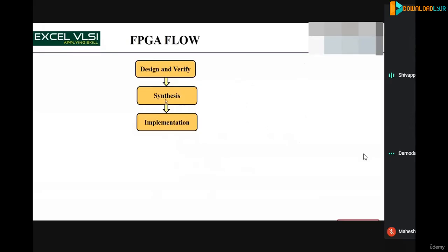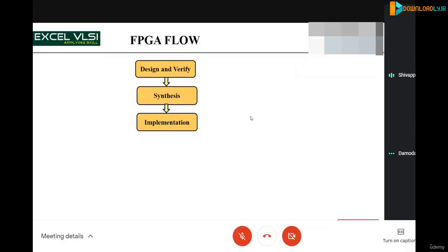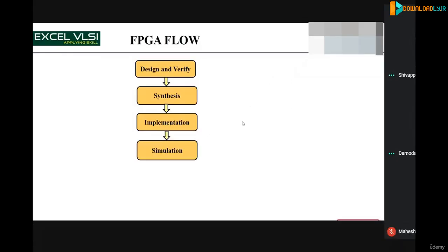And what does the fitting mean? Now you're synthesizing, and in the implementation stage, you're doing the fitment and the timing analysis, right? All these you do to fit this design into that particular FPGA, and you do the timing analysis. Now for the synchronous circuit, what timing analysis is, in STA you will learn a lot of it actually.